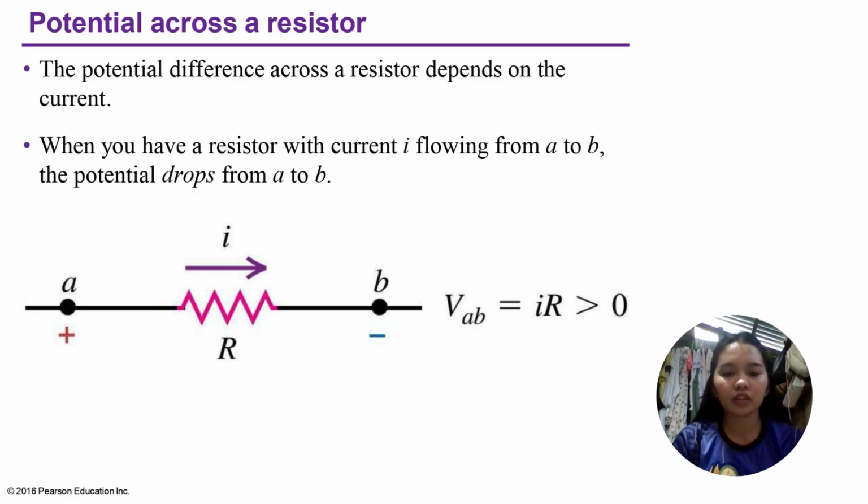So for comparison, let's briefly revisit resistors. Unlike inductors, the voltage across a resistor is directly proportional to the current flowing through it. As described by Ohm's law, V_AB is equal to IR. So the voltage and current are instantly related. Here the resistor dissipates energy as heat, while an ideal inductor stores energy in its magnetic field.